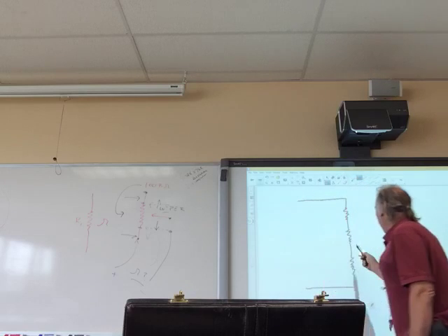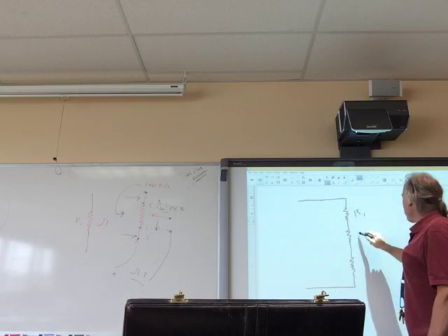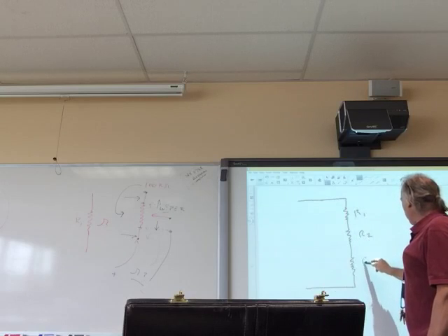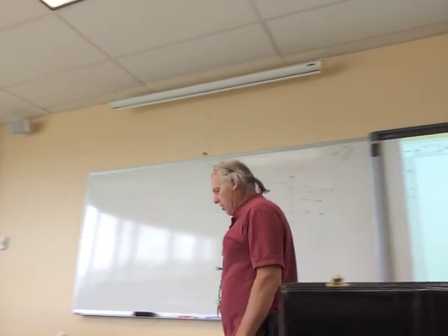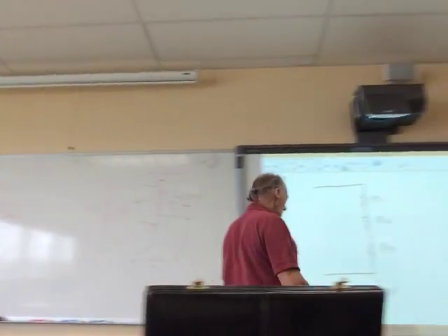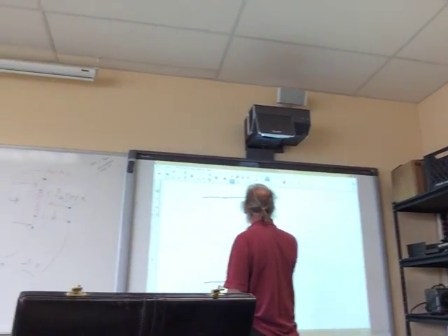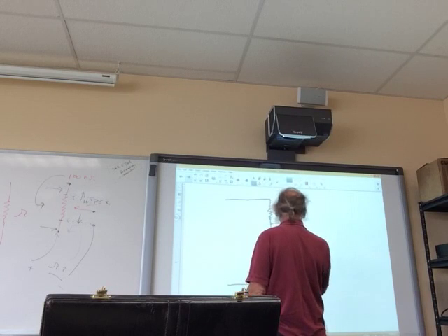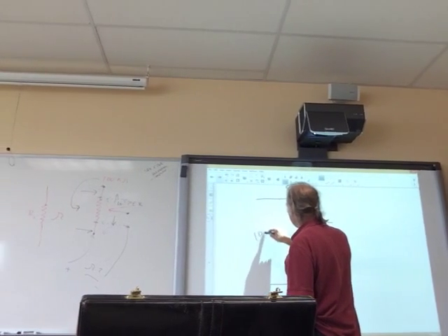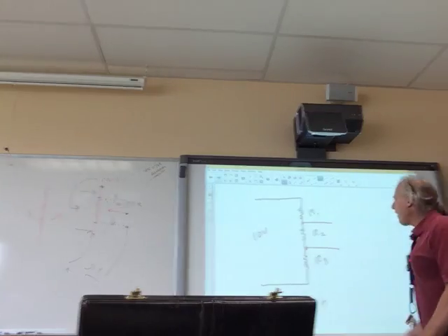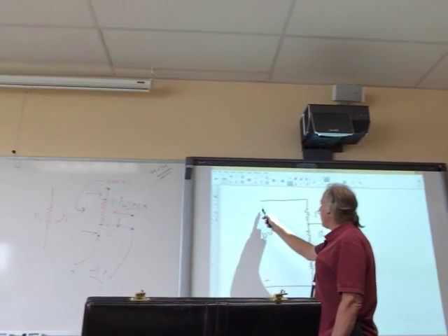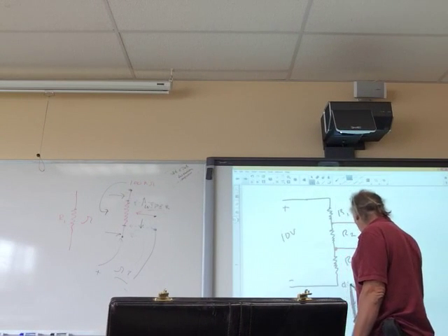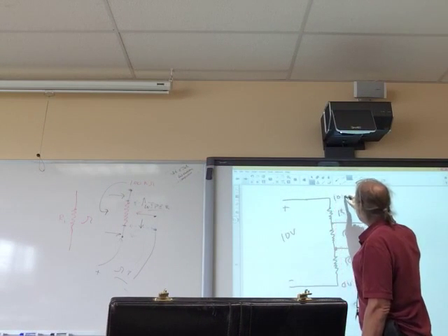Now, the actual resistors make up a resistor network, a series resistor network in this case, and at certain points, which we already know because we've finished doing some of that, I will have certain voltages. If I said this was 10 volts, then I know that this side right here is 0 volts, and I know that this is 10 volts.